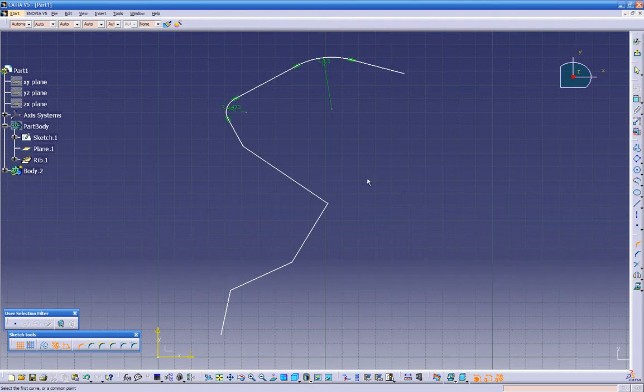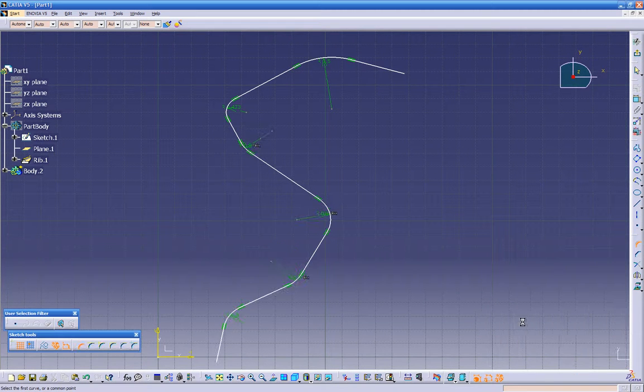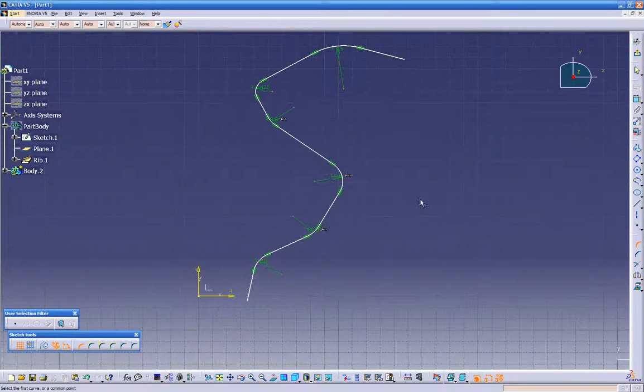1.5. Or we can highlight the whole area, and I got all the points highlighted if you see them. So right now, if I give it a dimension over here, that's gonna change all of them. So let's put ½ inch. And all of them it's ½ inch. But you see it's carrying the formula with the radius, because the moment I change this right here, automatically it's gonna update it because they're all linked together. So what will happen if I double click here, I change it to 800, automatically update all the other ones. So that's pretty cool right there.